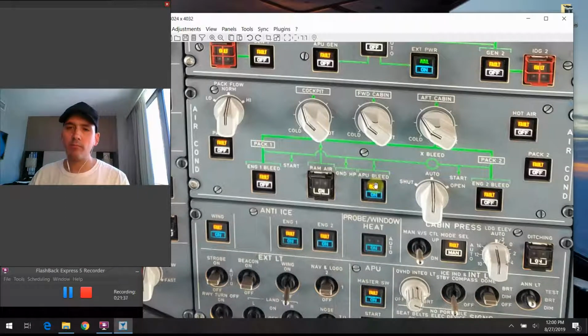And the last one, the ram air switch here, like we said, this is kind of a special one, and it did differ from those ram air NACA scoop inlets that we talked about a moment ago. This ram air system is there for the condition of if we had some kind of smoke or fumes accumulating inside the flight deck, and part of our emergency procedures required us to get that smoke and fumes out of there in an expeditious fashion, because it's obviously probably a dangerous situation if it's getting to the point where we're having a hard time breathing, we might have a hard time seeing.